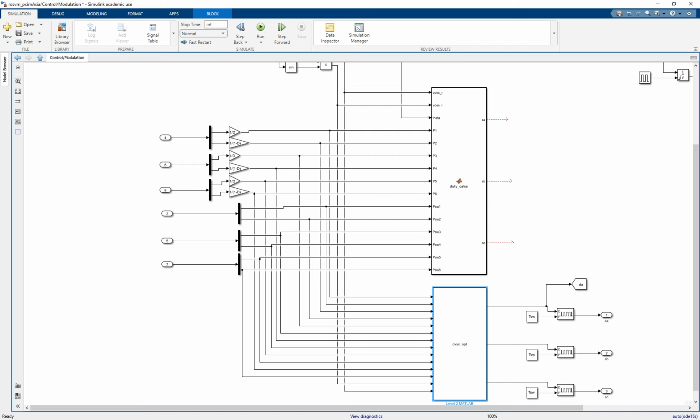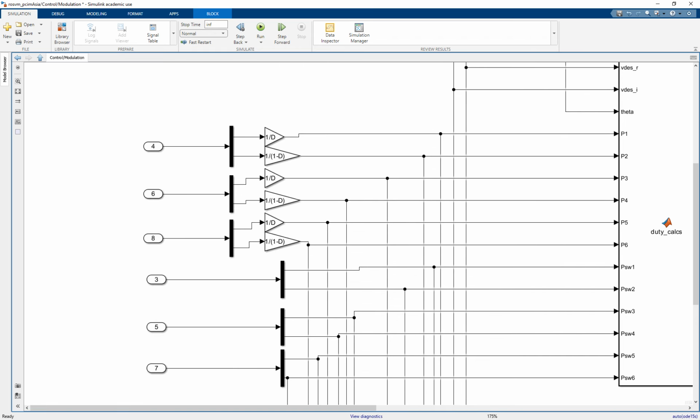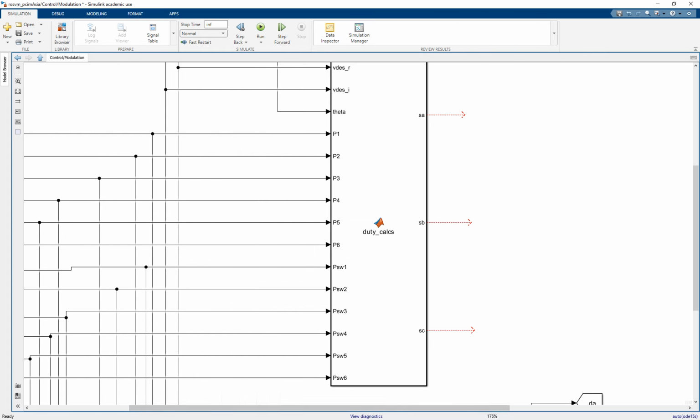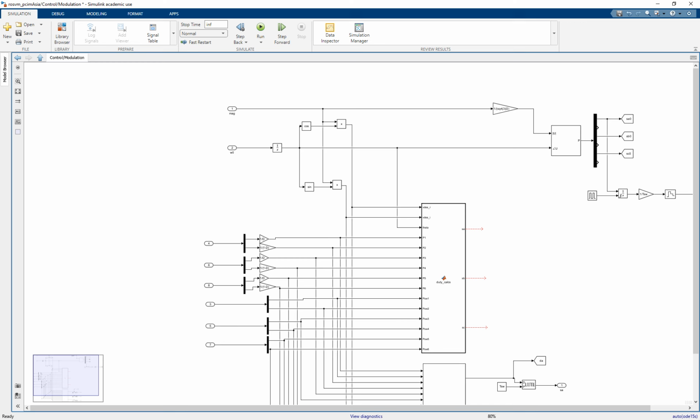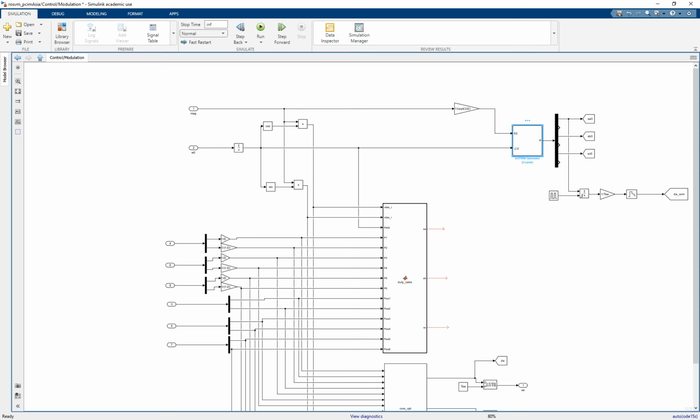And as I said before, the way that I calculate the power losses, especially for conduction loss, is that because they're already averaged out over the switching period by PLECS, I have to scale them by 1 over d and 1 over 1 minus d for the lower legs and for the upper leg to get the value of the peak of the power loss, and then recalculate my desired optimized duty cycles.